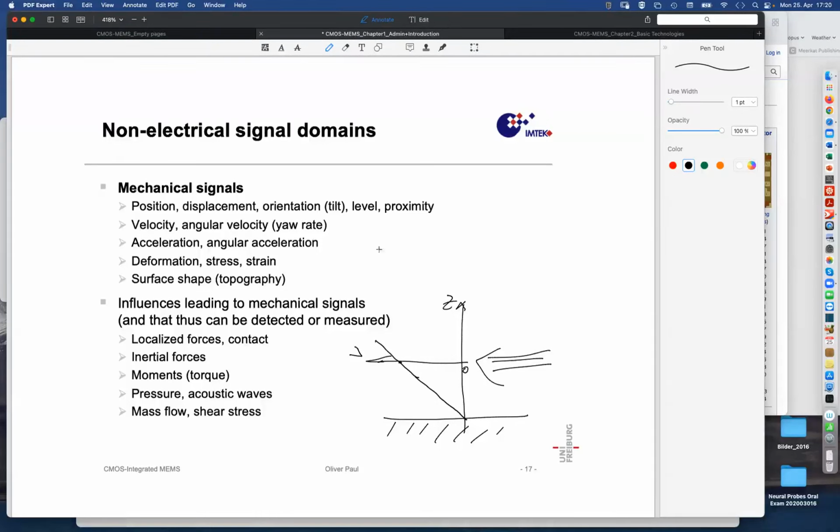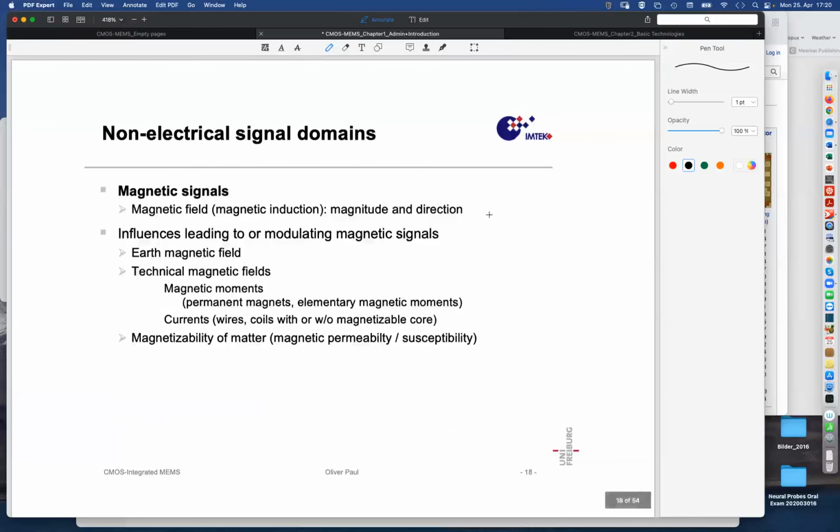If this is a pipe, or two planes with the fluid flowing in between, then you may have some parabolic fluid profile. That leads into the Hagen-Poiseuille law. You need to push to get the fluid through, and if you push, then of course you push also via the fluid on the surfaces with which it is in contact. So shear stress. But let me not get too much into detail here.